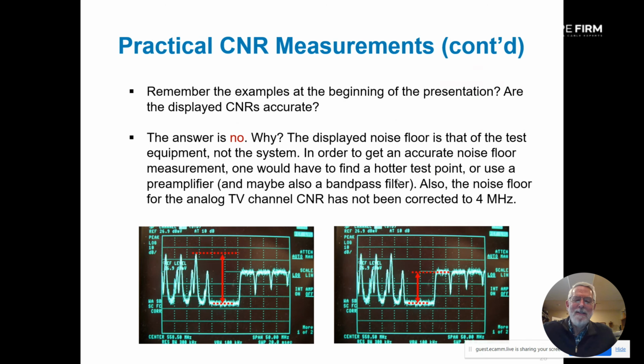Well, no. You have to correct for your resolution bandwidth. Well, that's one part of it. But the part that you can't tell from these pictures is your analyzer noise floor. You've got to do that unplug analyzer noise floor test, because these are typical drop levels, which are pretty low. And so you disconnect the RF input from the analyzer, and that noise floor doesn't move very much. So first of all, we're seeing mostly test equipment noise floor here. So we've got to find a hotter test point or use a preamp.